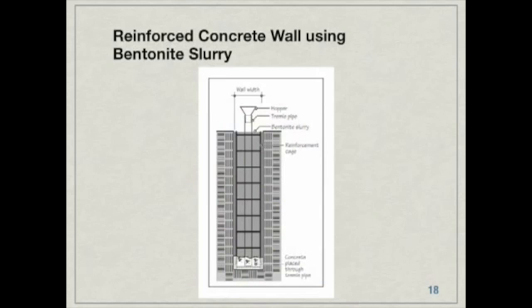Now, once the entire area has been excavated and filled with slurry, this is just a diagram of that Tremie pipe, which would be driven down to the bottom of the excavated area, and again, the concrete would begin to be pumped out of the Tremie pipe. As it is, the bentonite obviously rises, and as the bentonite rises, it is sucked off the top and pumped back into the trucks.